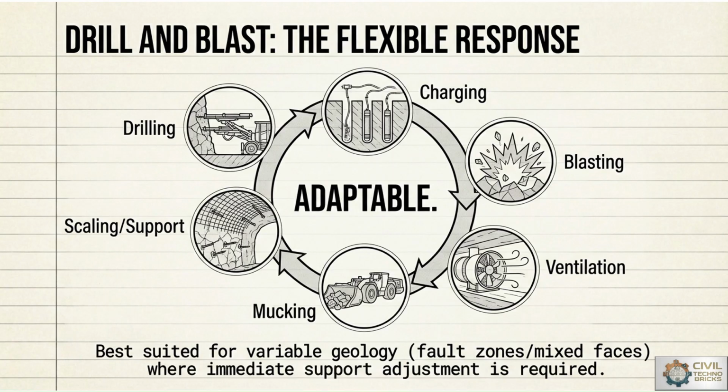So drilling and blasting, which is a physical and flexible response, is best suited for variable geological conditions, just like fault zones or mixed faces or the mixed type of rocky layer, where immediate support adjustment is required at the same time of blasting and drilling.